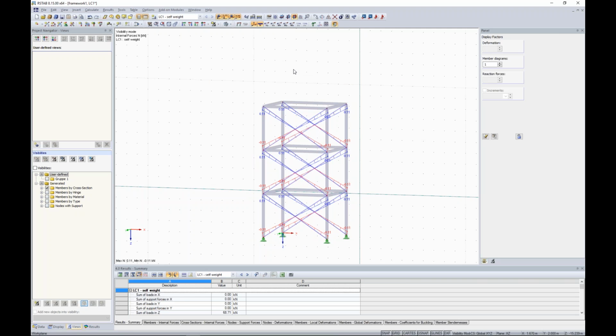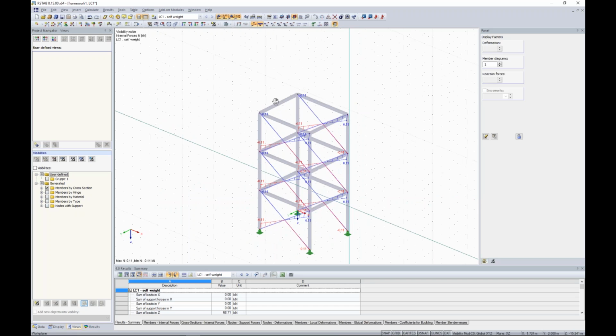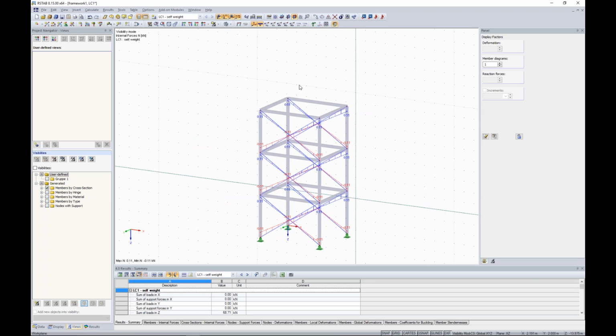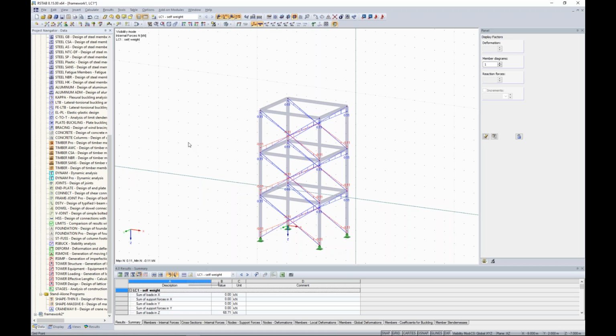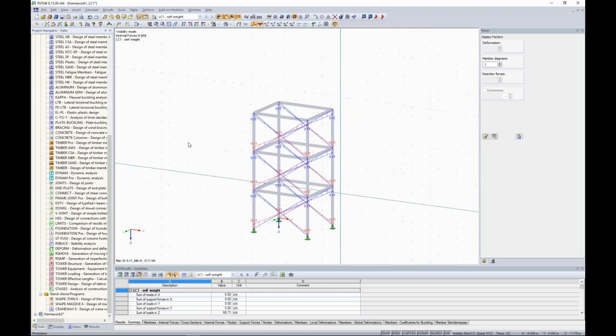Visibility, like here you can see that all the tension members are still in the structure. That means they just have a reduced stiffness if they have some compression. And both of the options in this example lead to final results. And with that said, we can just continue to the next example.